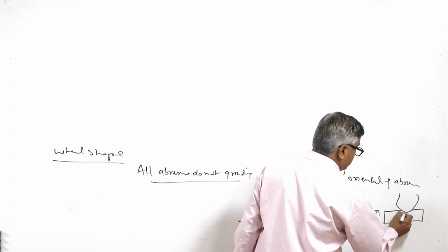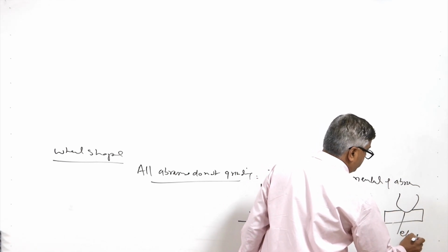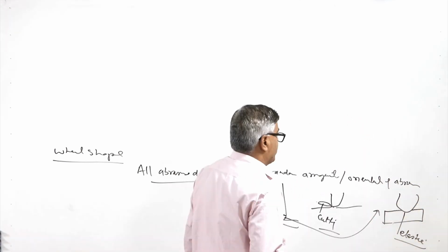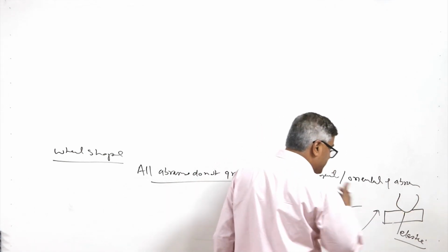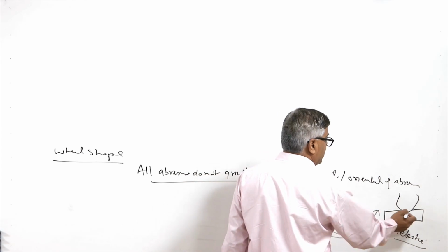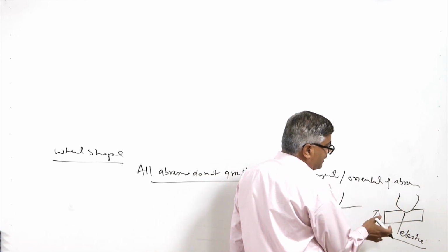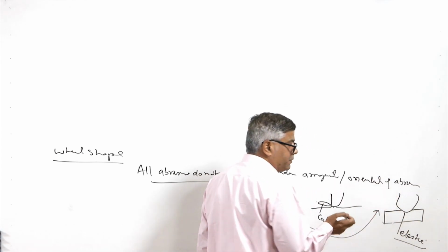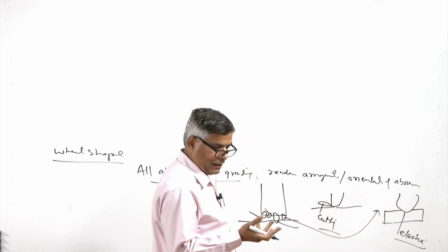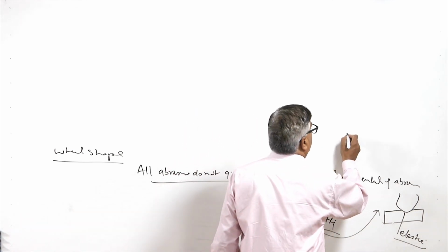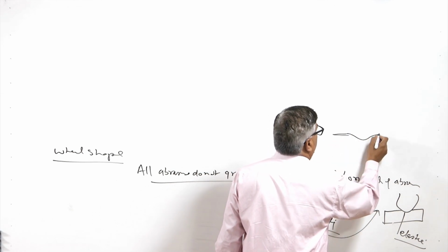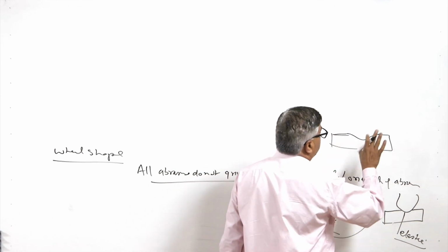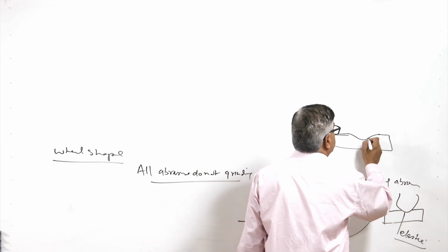So, this will be leading to the elastic deformation of the material, not the plastic deformation, or even if there is plastic deformation, shearing is not facilitated. So, in this case the material is getting deformed, but it is not sheared off due to the rounding of the abrasives, and we find an impression on the surface of the workpiece of this kind, wherein the groove is formed, but material is not removed, only displaced.